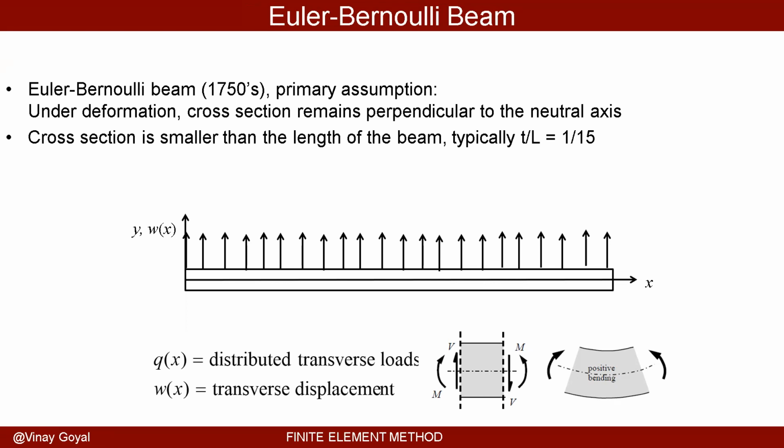This was covered in a mechanics of materials course, but perhaps they didn't go into the level of details required to understand this theory further. The beam is subjected to a distributed transverse load. It has a transverse deflection that I'm calling W of X. And if I look at any cut here, like a free body diagram, you will have a shear load and a bending moment that's reacting the external loads.